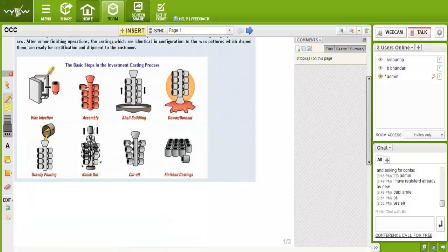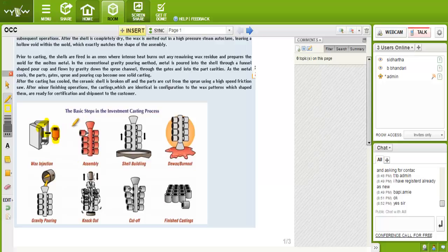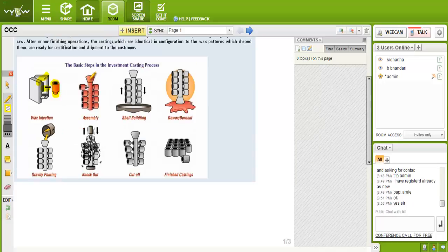See, there is a box. By using this box, we can create a pattern. Inside this box, we pour the wax. See the red one, and finally we got this. We use this as a mold. Okay, pattern. See, there is a stick, and we attach the patterns that way: 1, 2, 3, 4, 5, 6, 7, 8.